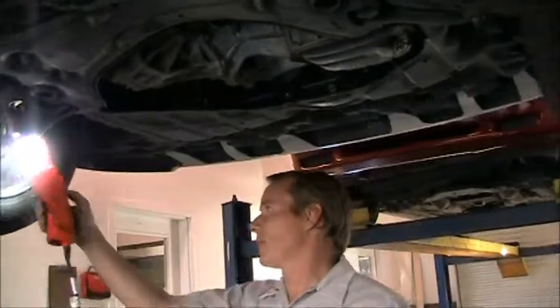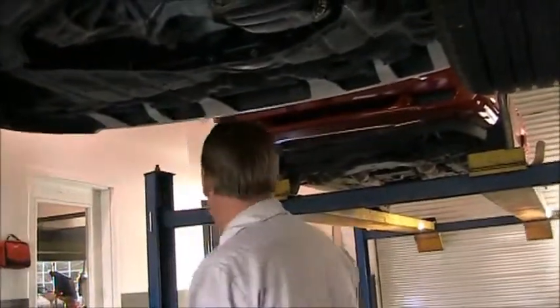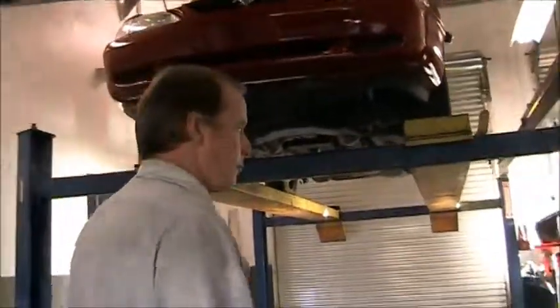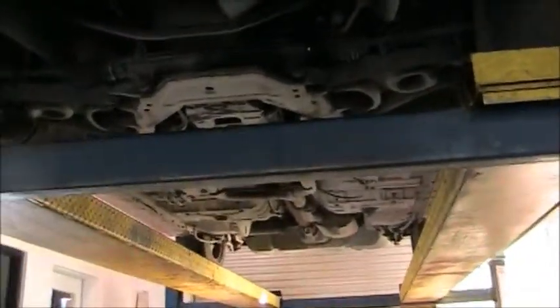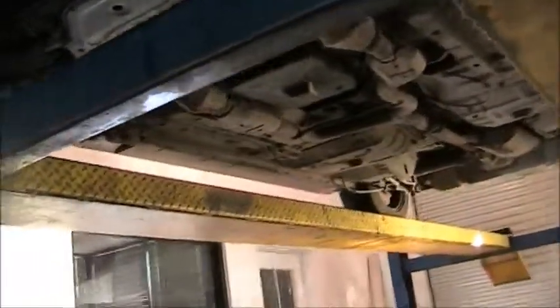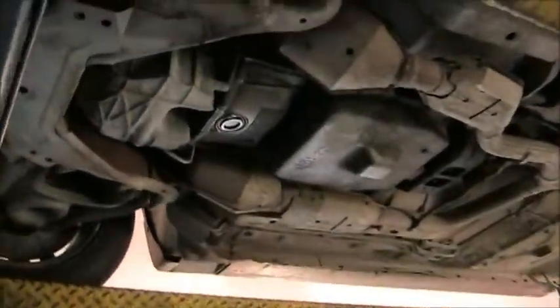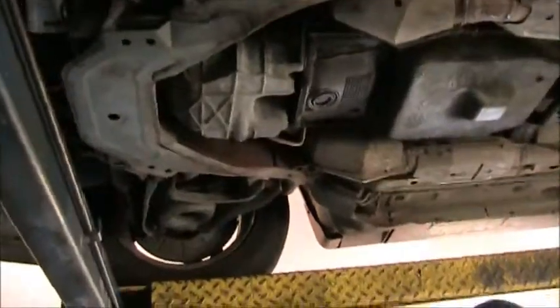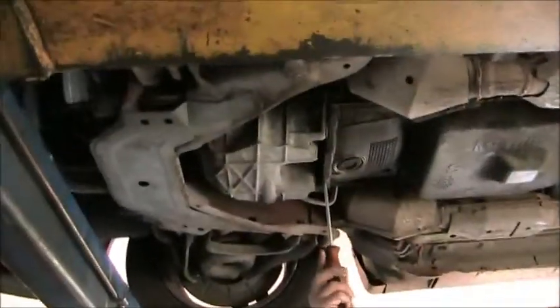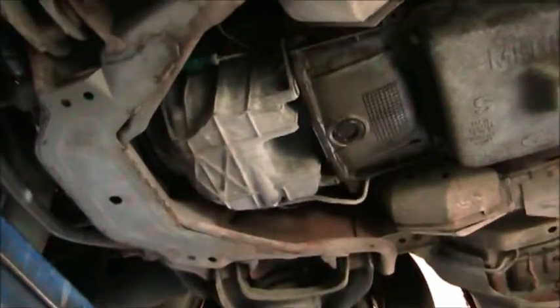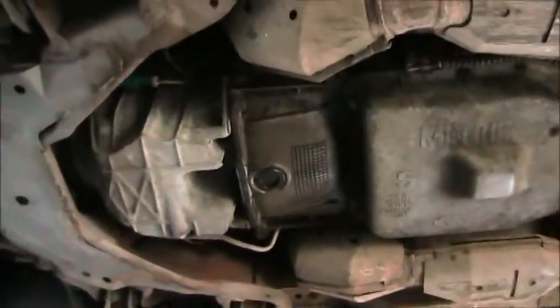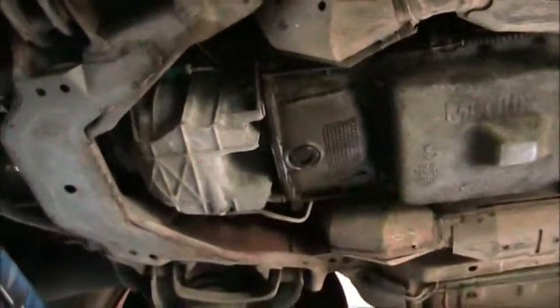Now we're going to move over here to a conventional front engine rear wheel drive with the transmission. We'll see how the lighting is if we need a drop light over here as well. So, just like what we have over there on the ground, we have a transmission, a bell housing. In the bell housing there's a torque converter, which is a fluid coupling between the engine and the transmission. The torque converter allows you to sit at idle with it in gear and not go. Once you depress the throttle, the torque converter engages more.